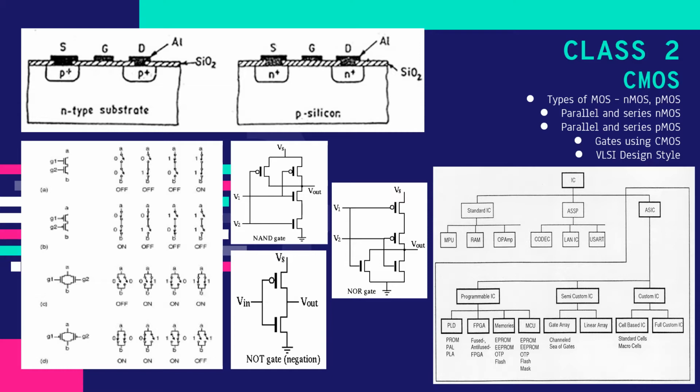In class 2, we also covered Moore's law, logic gates, and CMOS. In CMOS, we learned how an NMOS transistor, if the input is 1, then the switch is on. However, for a PMOS transistor, if the input is 0, the switch will be on. So the source of a PMOS will be positive and the source of NMOS will be ground.